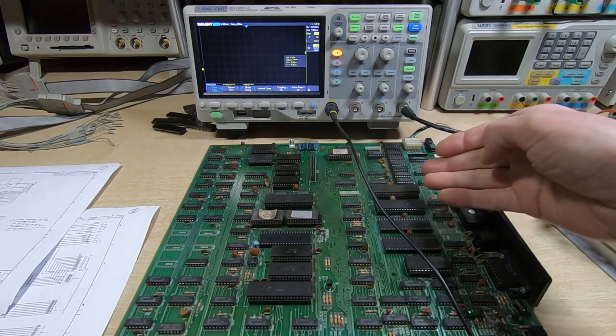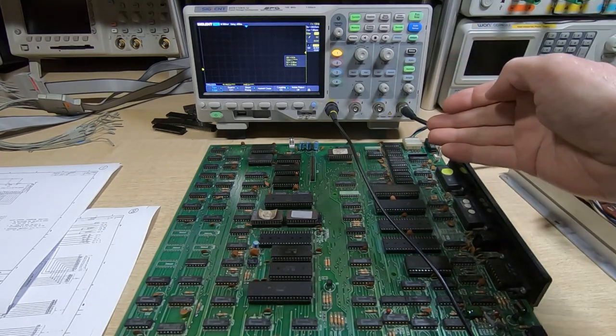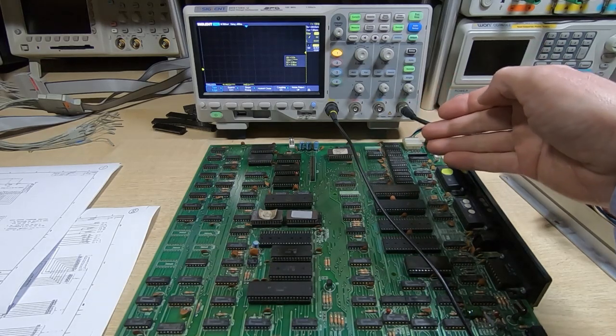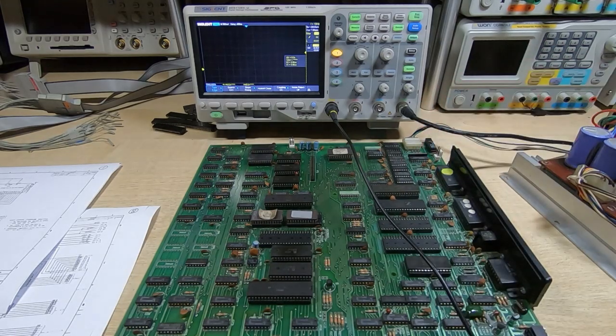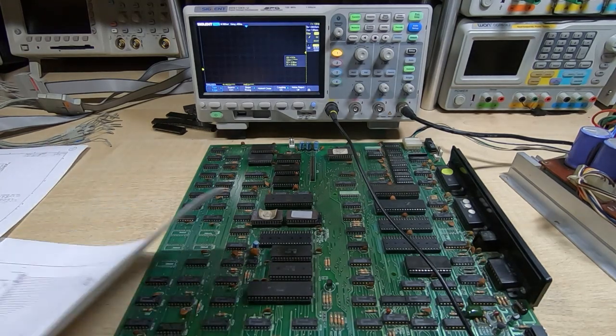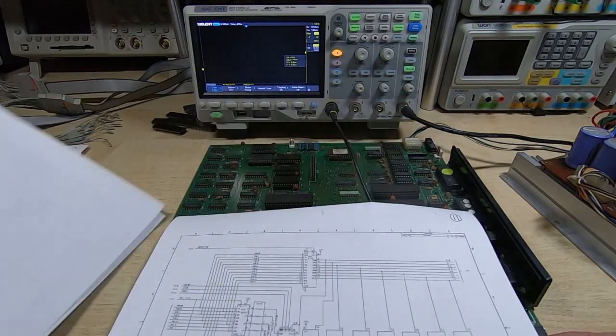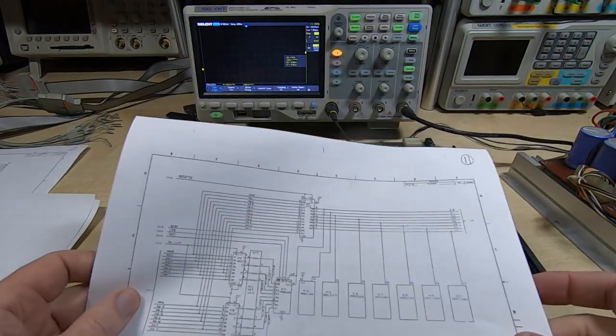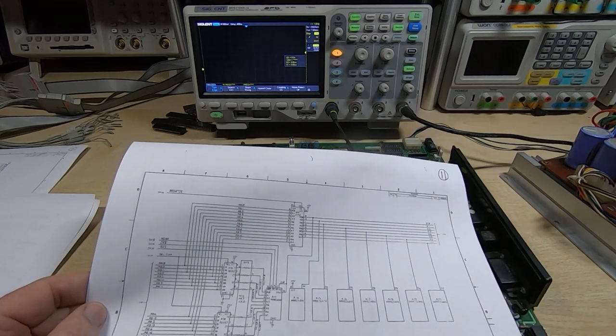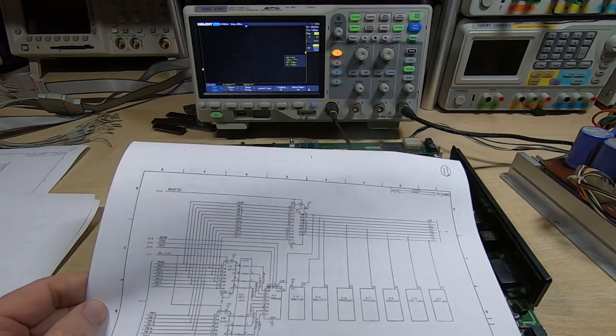Every time it goes through the self-test, the value it's returning for the first byte that it's tried to write is 0, so that's obviously wrong. So getting the correct section from the schematic, find the RAM, and there's a bit of a clue we've got already that it's always a 0 value that's returned.